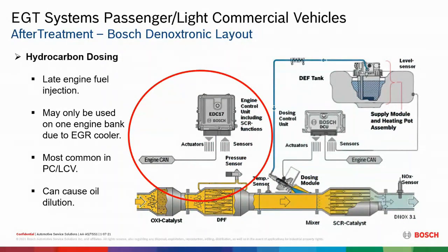And again, diesel engines, injectors, when they start to wear, even if it's a piezo injector or a solenoid, it's going to start injecting more fuel in most cases. So keep that in mind. More fuel is going to cause problems.